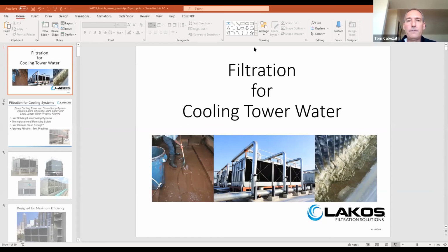The purge valve itself, if you're dumping water, kind of goes in conjunction with the water you'd blow down anyway. But the perception is that you continuously dump water, and that's not the case. We might lose maybe 20 to 40 gallons of water once a day if that's actually purged. So if they know that there's going to be maintenance issues or the guys aren't going to maintain bags, I would automatically go and use the ABV, or the auto blowdown valve, versus the bags.